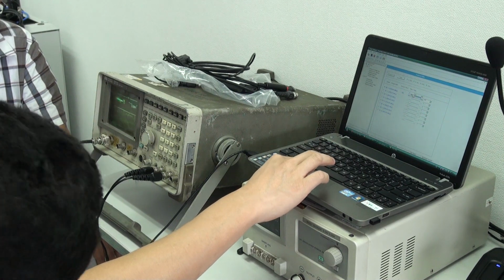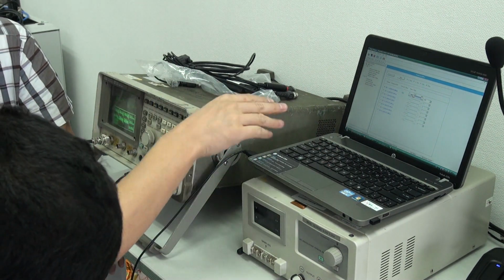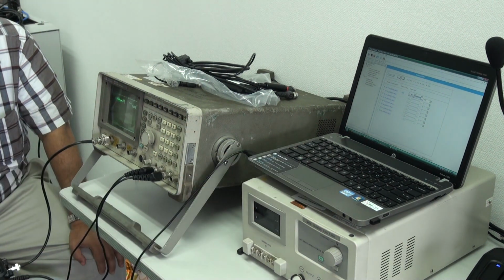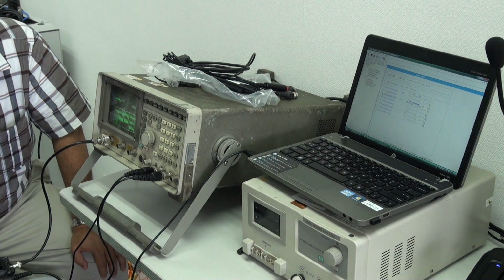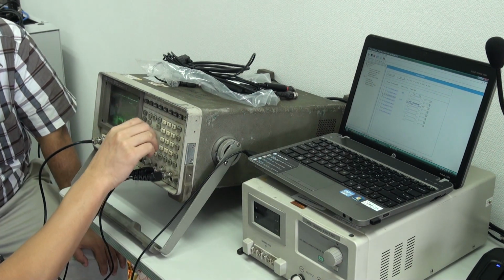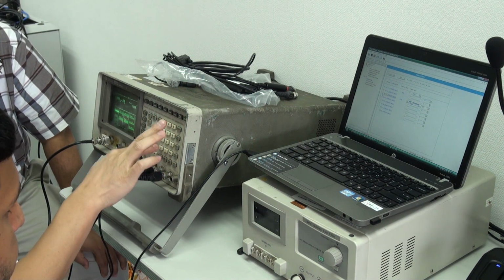DMR only first time. And then you just click save. Okay. Remember, after you finish tuning for every item, you must save. Okay. And then you go back to another one, for example, to this one. Right now you need to change the frequency. Yeah. That is 350.075.